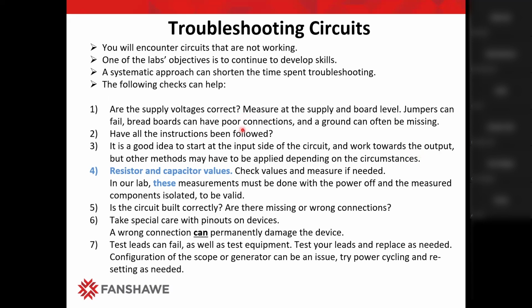And you can go forward or you can go backwards with this, following the signals and see at which stage the signal disappears, and then you're going to have to address the problem or solve it. Come up with a solution. It's a good idea to do that, but other methods might be applied depending on the circumstances. Resistors and capacitor values: check the values and measure if needed.